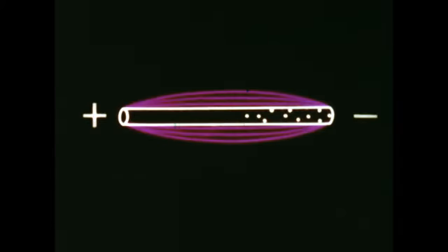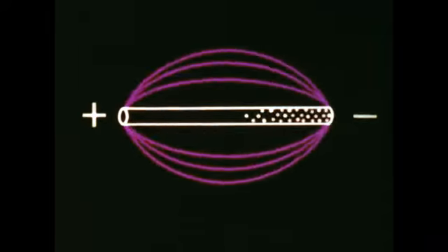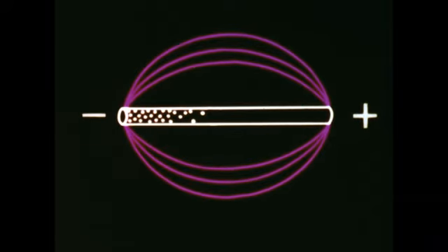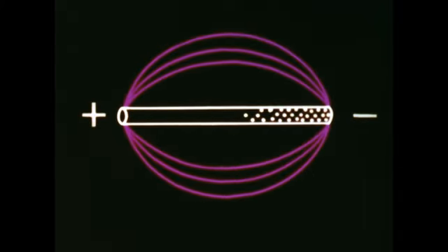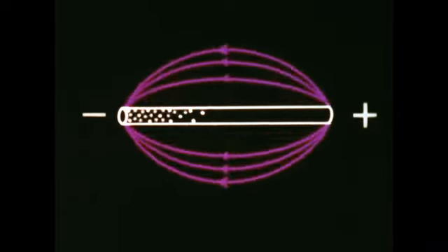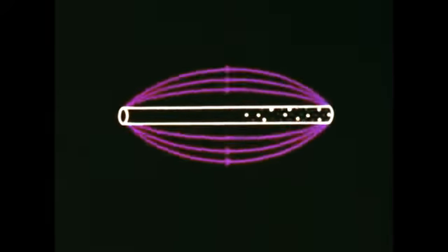This changing polarity produces an electric field in phase with it. When the voltage is of this polarity, the field is in this direction. When the polarity reverses, the field builds to a maximum in the opposite direction. This is known as the E field. The E and the H fields thus build and collapse 90 degrees out of phase with each other and constitute the antenna's immediate field.